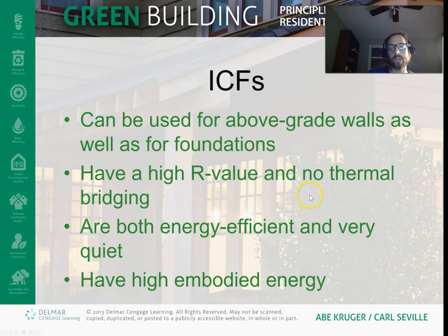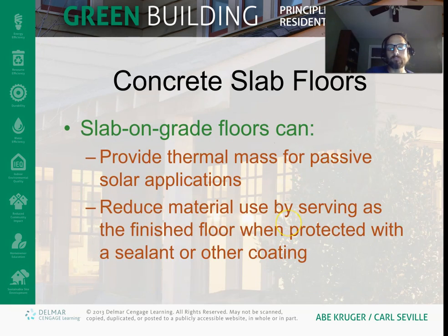So there are some advanced versions of this, like an ICF, which is an insulated concrete form. They use these for foundations. It's kind of like the structural insulated panel, but the outside is foam and the inside is rebar. They have rebar and they fill that with concrete. And so then you have basically the structure and the thermal mass of concrete, but also with some insulation. But you can also build walls with them as well.